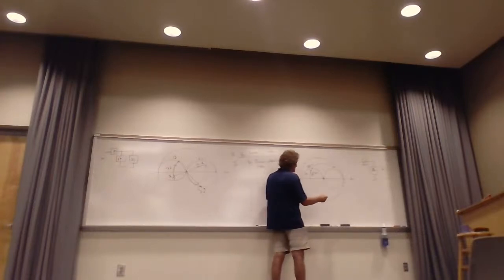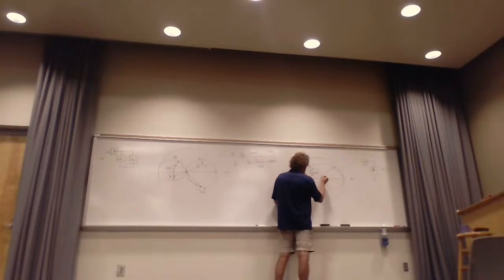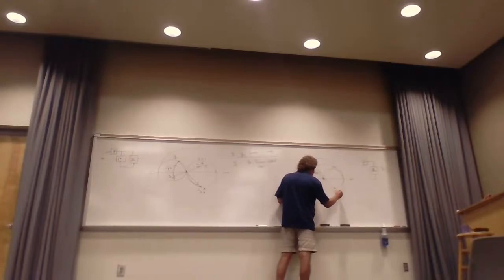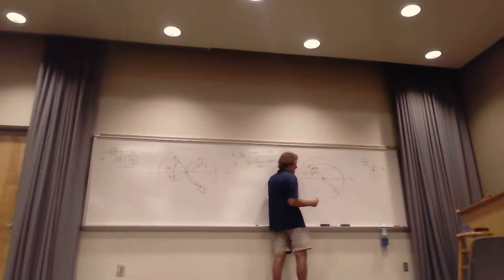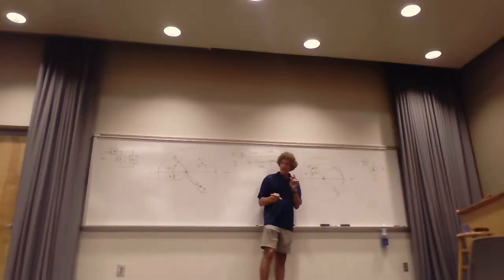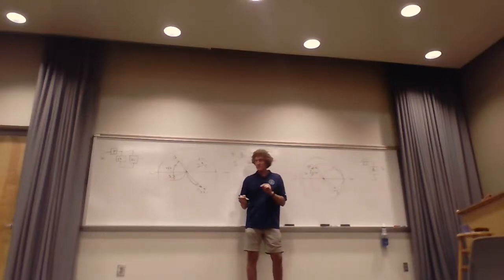Now, you shoot down here to the conjugate point. So this was Z, now this is going to be Y, which is 1 over this Z2. Call this point Z2, right? Now that's an admittance, right?